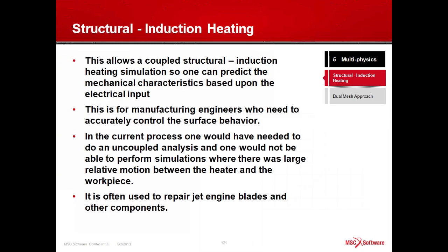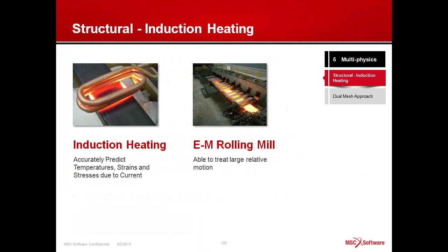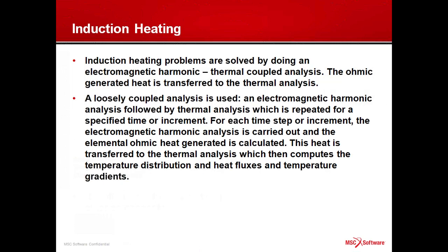Finally, I want to quickly talk about induction heating. Induction heating is something we've had before. Now we've combined it with structural analysis. Typical applications are in manufacturing or heat treatment, or in problems where you want to control very accurately the temperature on the surface. By controlling the temperature on the surface, you can do things like case harden the material. This is done using a harmonic electromagnetic analysis or a harmonic magnetodynamic analysis.